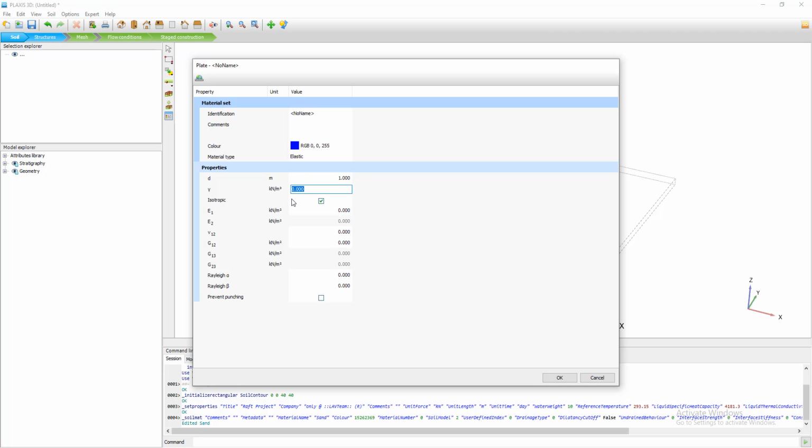So when you add the unit weight of the raft here, you have two ways. Either you just ignore the unit weight of the raft because we're adding it as a plate element. If we add this as a plate element, there will be a substitute from the weight of the soil compared to the weight of the plate or the concrete, but we are underestimating the weight.